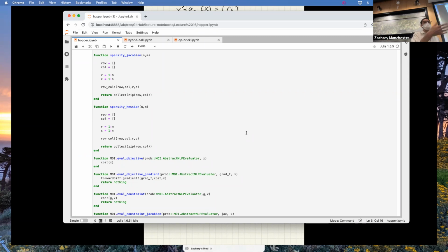Usually, practically on most of these robots right now, people are doing MPC. So usually you'd have something like this, and then you'd track it with one of these QP-based MPC controllers. In that controller, you'd have a bunch of stuff to handle disturbance rejection, like if the foot slips, push recovery. There's a lot of stuff like that in these online feedback controllers. Does that answer your question?